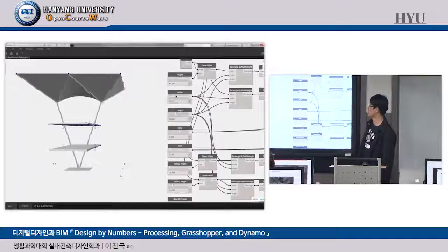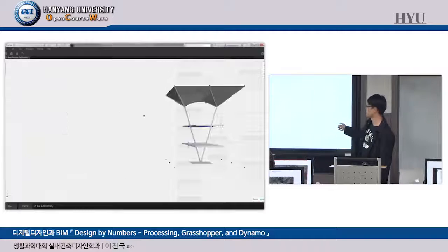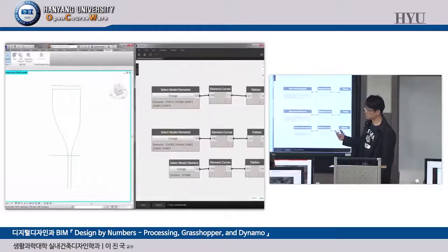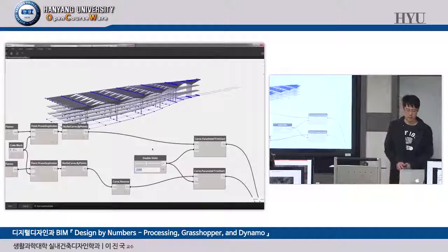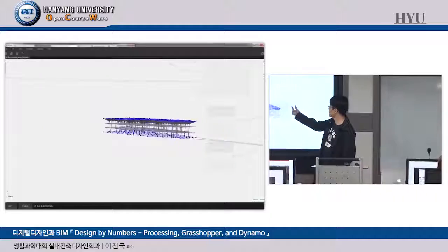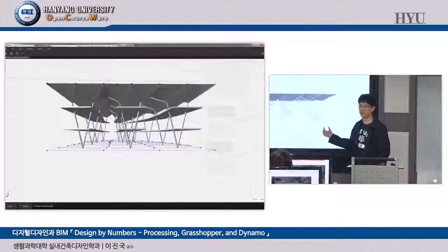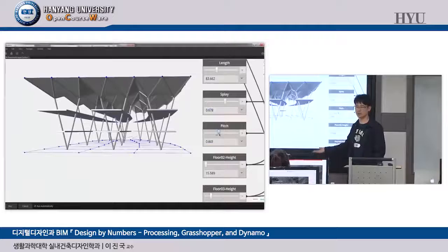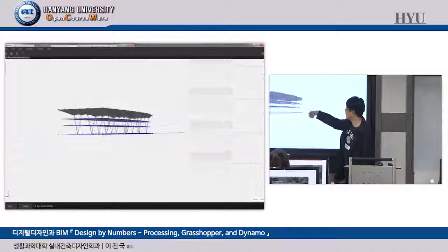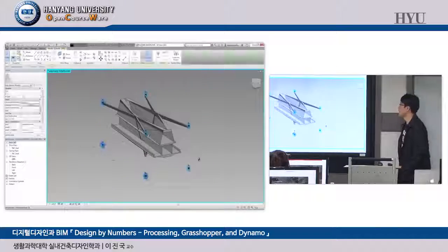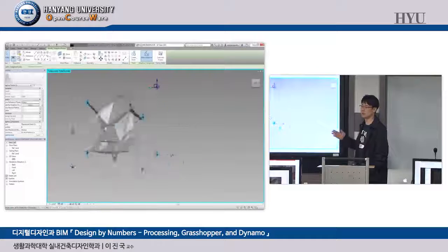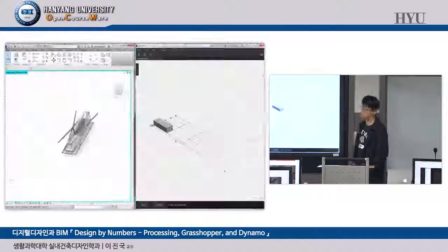So let's take a look at the Dynamo nodes. They look very complicated, but manageable. You can do that. So watch this video, okay? The one single elevation structure can be copied in the X direction and Y direction, recursively, in order to control the slab and the rooftop structure and some details and so on. Entirely managed by the BIM application, Revit, okay?